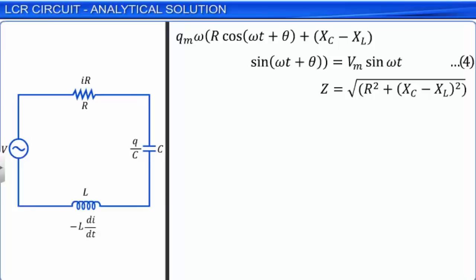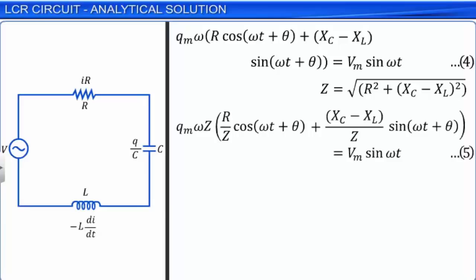If sin phi is the difference of capacitive and inductive reactance divided by the circuit impedance, that is, sin phi is equal to (XC minus XL) by Z, where phi is the phase difference between the instantaneous current and the voltage, then cos phi gives the relation between the resistance and the circuit impedance, that is, cos phi is equal to R by Z.